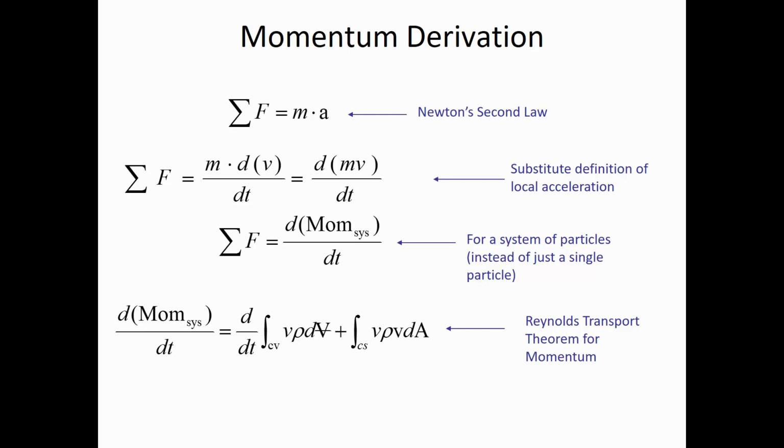So what this Reynolds transport theorem is saying is that we can apply this mass balance idea, and inside of the control volume there can be an accumulation of momentum. If this jet that's coming in and out, for instance, is hitting some sort of an impeller, then when the stream first starts, it could cause that impeller to start spinning. Well, maybe it's attached to a flywheel that retains the momentum, and then even if you switched off the jet, that flywheel would continue to spin. And so that's an example of how inside of the control volume, momentum can be stored.